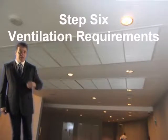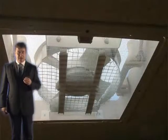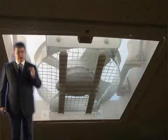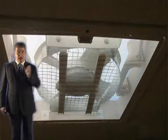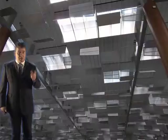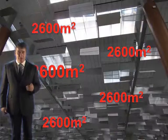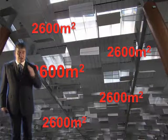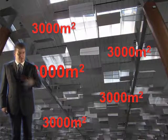Now you could use either natural ventilation or mechanical ventilation. Now in this case, mechanical ventilation has been decided on. So now we need to determine how many reservoirs we need. So we've got mechanical ventilation. How many reservoirs do we need? Well, the largest size of reservoir in a mechanical system is 2,600 square metres. However, this can be increased to 3,000 for property protection only. So you can increase it if it's only for property protection.